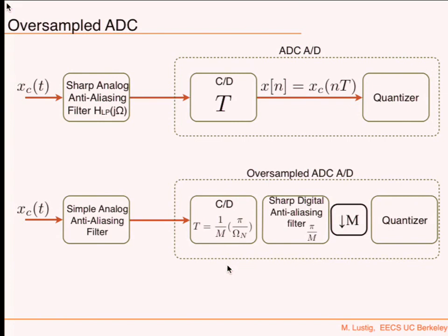But the question is, what is more advantageous in terms of designing a system? And often the second case, for the flexibility of being able to not have to design a very sharp filter, you can do a lot of things in software. That's much easier to change. And so this is sometimes a much better trade-off. Okay? So you add some computation for the purpose of better sampling.